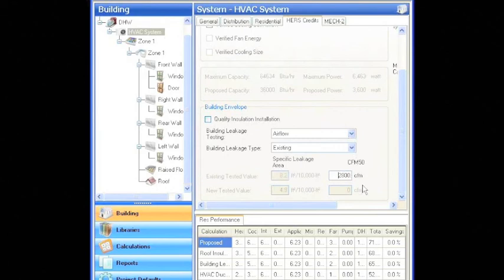Make sure when you fill things in, people, we've had comments from users that sometimes you type in a number and you click somewhere else in the model, and when you come back, the number hasn't stuck. If you are having trouble with that, do let us know, or you can let EnergySoft know. We try to push those comments over to them so they can fix those problems. What I typically do, just to make sure that it was recorded, is that when I enter in something, I also click somewhere else on that same screen. So maybe I just click on the pull-down menu to make sure that it's remembered the number I just typed in.